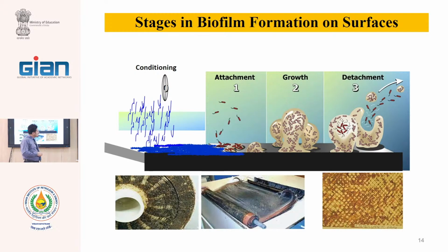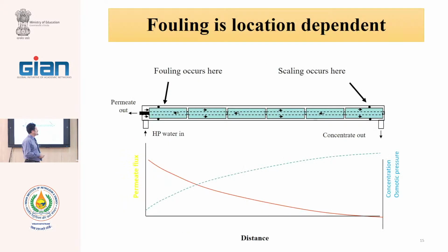This shows that when the microorganism can reach the RO membrane surface due to the bad performance of the sand filter, cartridge filter, during maybe 1 month, the membranes are completely destroyed, and you see the color of the membrane change from white to dark brown. Therefore, biofouling is very bad fouling and can grow rapidly.